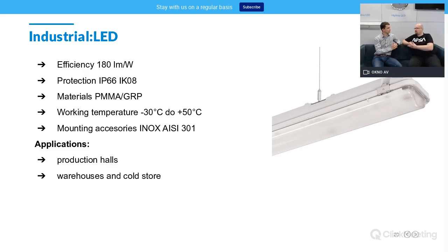Plastic clips for these kinds of products are mostly made of ABS plastic, which degrades very fast with chemical exposure. Even if you use only a mild solution when you clean them, over a few months or a year or two, these clips become brittle and they can crack, they can fall apart, they can fall from the luminaire. And this is another problem.